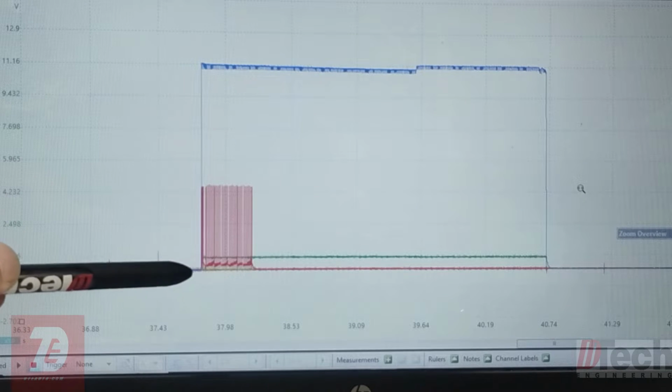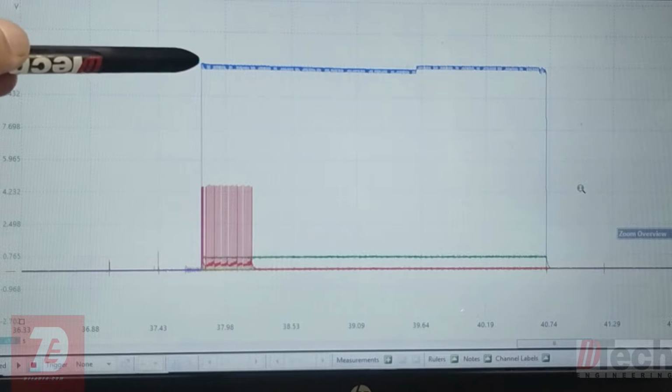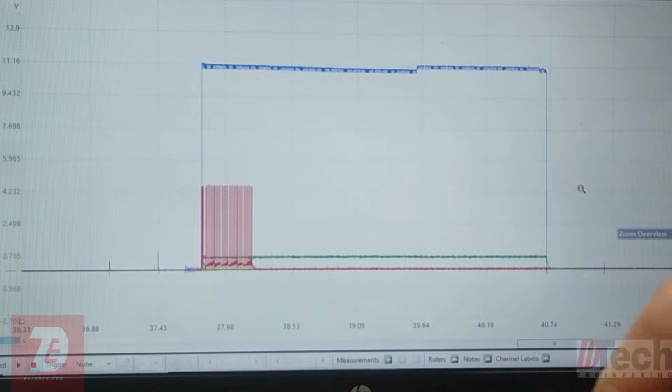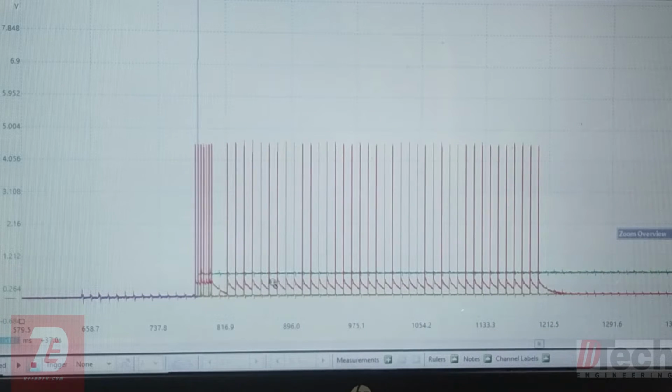This is happening, and then obviously we know the other circuit, the other side, the other wheel is good as far as its power supply for going out towards the sensor. So there is something going on here on this circuit for the front right, and obviously I don't know what I'm looking for, but that looks like some sort of activity, like the module attempting multiple times to get the circuit going, let's say.